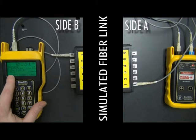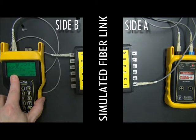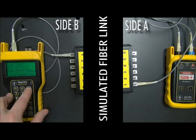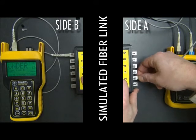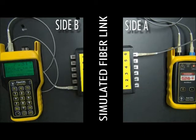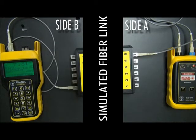What you will also see is that the fiber number got reset to port number 1. FiberOWL does this as a convenience, to make sure that all of the fibers maintain their sequence. So we're starting at fiber number 1, and again we just do our store and save. I'm going to do that for all the fibers. So now we've stored all of our readings at 850 and 1300. We know that a couple of 1300 readings failed, so we need to troubleshoot and find out what's wrong with those cables. But we have all our readings stored.